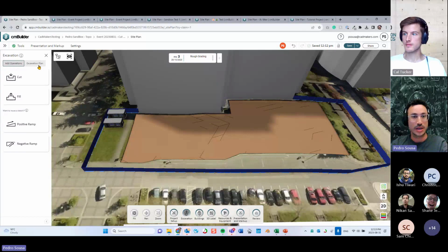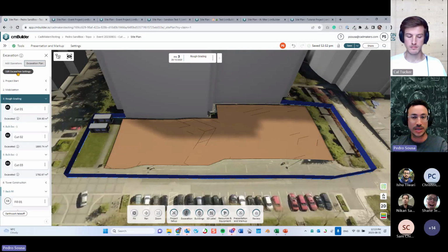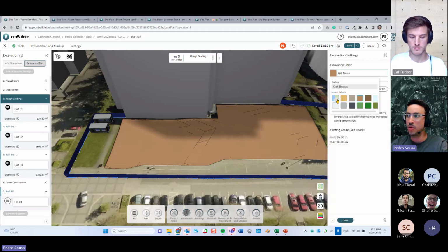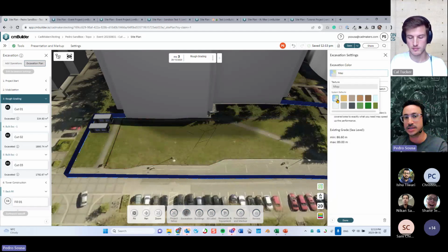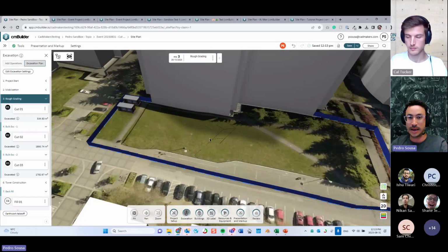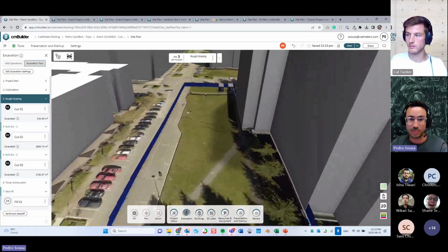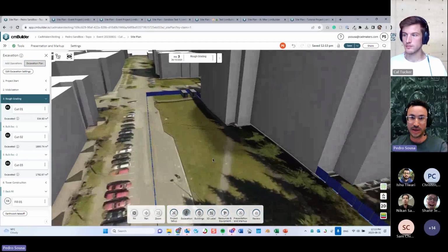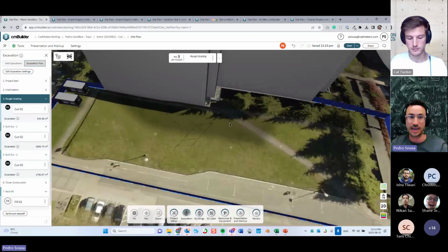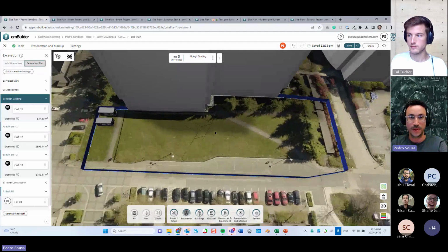excavation plan colors. So we're going to go over here, my excavation plan, in the edit excavation settings, I can turn my excavation color to follow whatever is on the original background. So if there are any zones, labels, lines, drawings, or anything projected on this area for the excavation, it will show those objects projected in here, because it's taking whatever is on the original background and putting that color on your excavation, right?